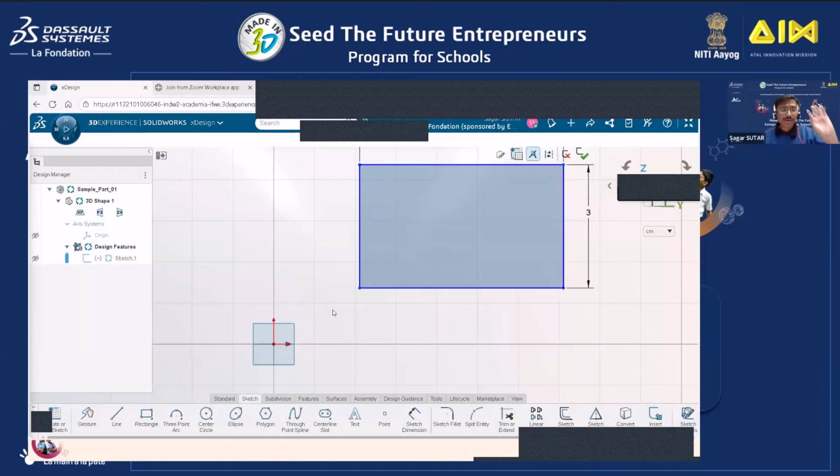I will show you how you can add geometrical relations. I'm selecting the point, pressing the control key, selecting another point and releasing the control key. And I will have coincident, vertical, horizontal, various types of relations.